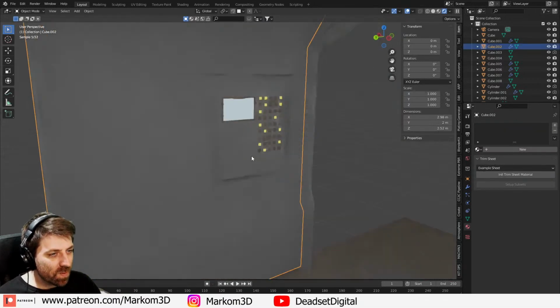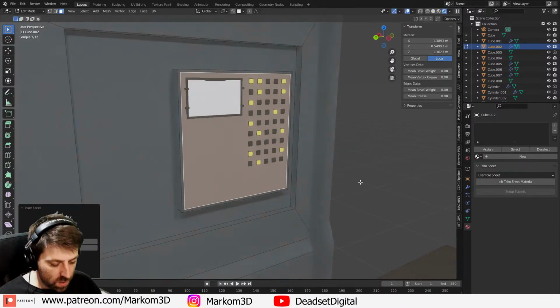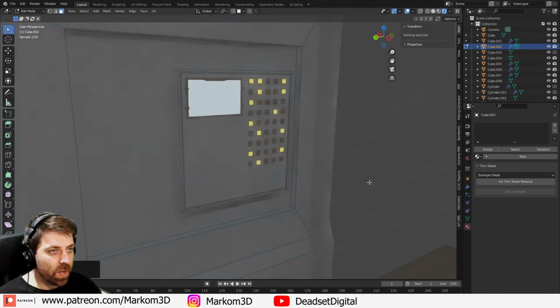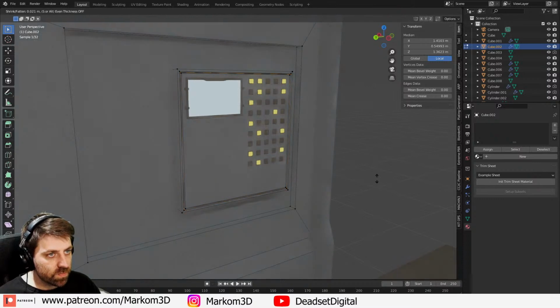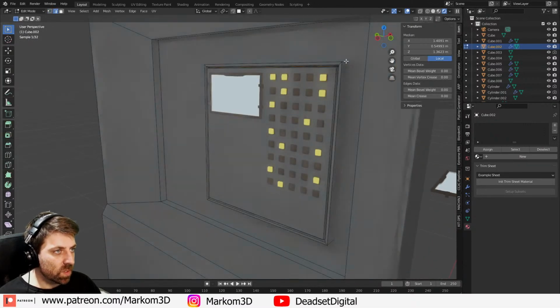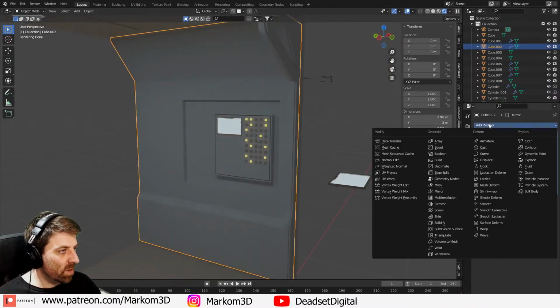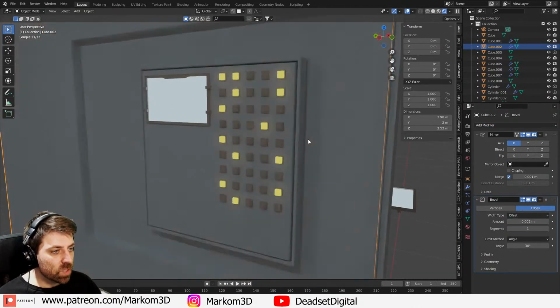From here, I'm not feeling this panel. I think what we might do is I'm going to press I to do an inset. Let's do Control B to do a bevel. Control numpad minus. Alt. Ugh, you suck. Let's Control numpad minus. Get rid of that inside selection. Alt S. V to rip. And so now we've kind of got this panel. Yeah, like that. That seems a bit better. And then obviously once we throw on our bevel at 0.002, that'll just look a little bit schmicker.